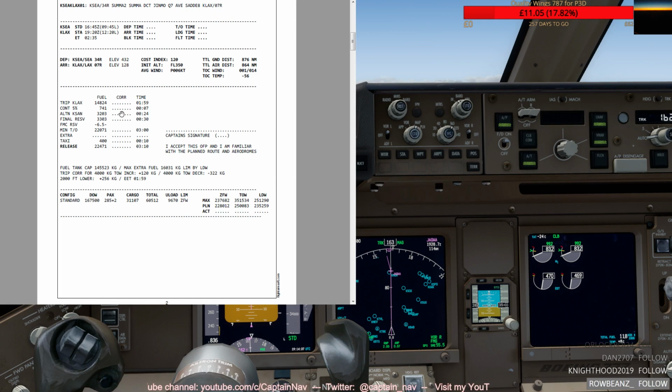No, you can't. What you can do is say, okay, I'm concentrating on the arrival on the destination airport, and I'll use some of the diversion fuel to allow for a longer approach or more fuel burned, to stick to the destination instead of diverting straight away.